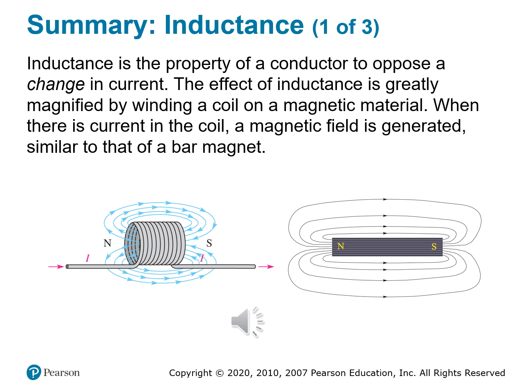So in essence, inductance is a kind of inertia for current. Just like mass resists changes in motion, inductance resists changes in current. And that's why inductors are used to filter, they're used to smooth signals, they store energy in switching power supplies, and they help shape timing in analog circuits. So let's go ahead and continue with the next topic.